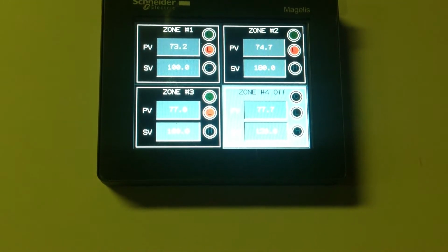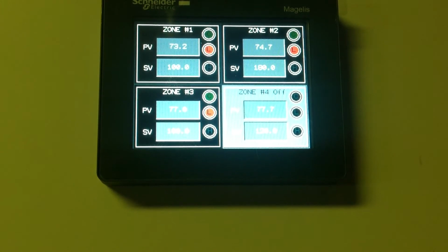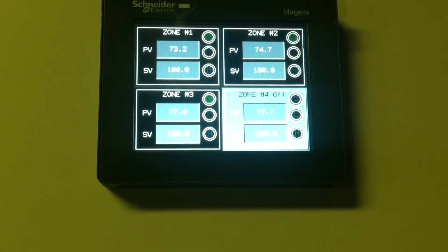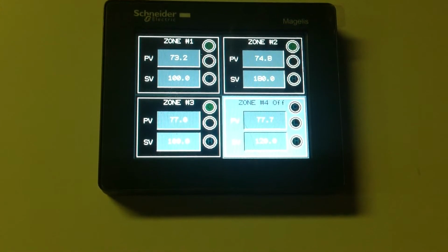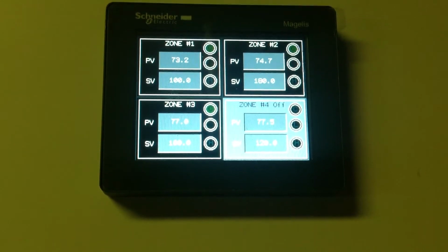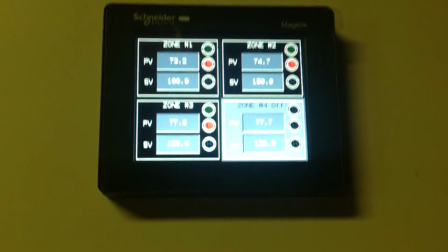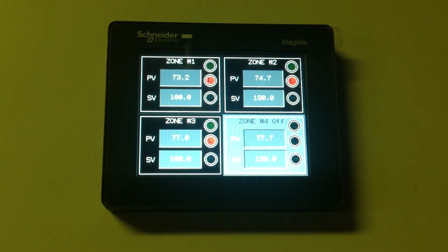We don't get any temperature control. We don't get alarms. We can't change set point and do all our settings. We just can't initialize any outputs. This is not a safety off. This still has solid state relay, which solid state relays can provide a small voltage regardless.